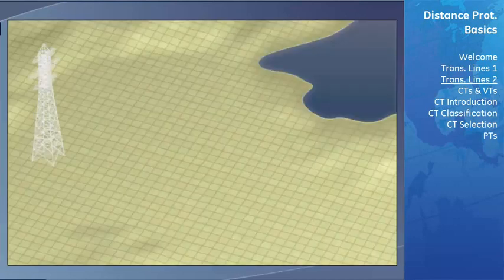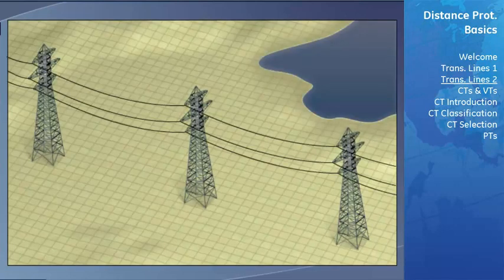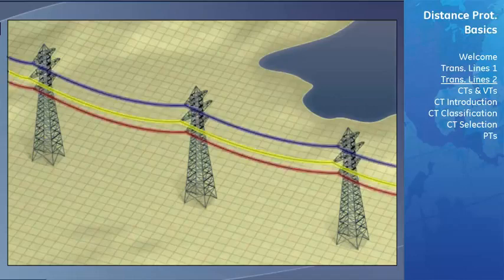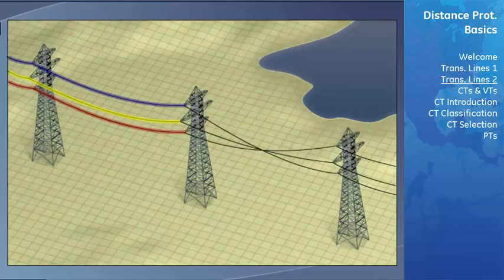Transmission lines in fault calculation studies are generally considered to have conductors where all three phases are symmetrical with respect to each other and the ground. That is to say, they have identical characteristics. However, in the common configuration where all three phases are hung vertically, as seen here, the characteristics of the different phases are not actually symmetrical due to the difference in height of each phase. This is the reason that some line sections are transposed, where the order of the transmission lines is reversed so that these characteristics differences can balance off and the total line can be approximated as symmetrical.